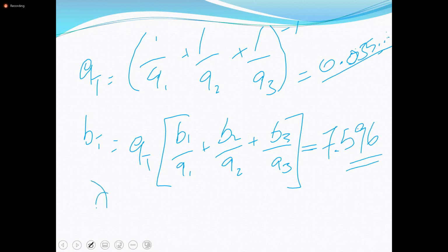You're now going to find lambda, which is equal to AT PT plus BT. Once you have found lambda, you are going to substitute lambda being equal to lambda 1. So you use the equation for lambda 1, lambda 2, and lambda 3, and you find P1, P2, and P3.